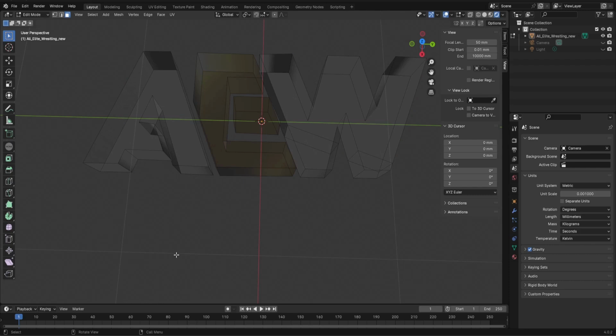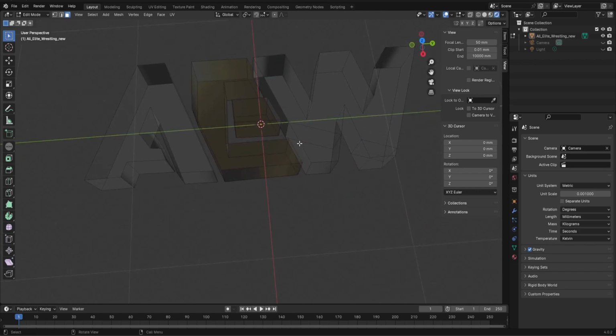So if you're ever in a virtual world and you notice that your object's for some reason transparent in a place and you can't work out why, because on the object it isn't, it's because the texture's on the inside, not on the outside. To fix that, you just press Shift plus N, and you want to do that at the end of your project every single time. So I now know all my normals are on the outside and the texture will show for me. Right, so now we're happy with it. This was one way that we could do that particular lift. Let's have a look at another way.